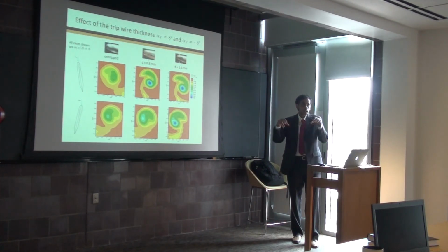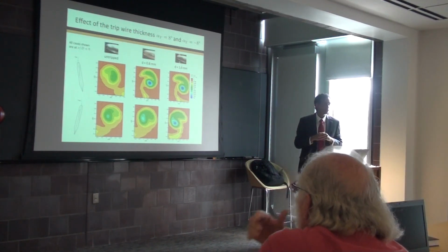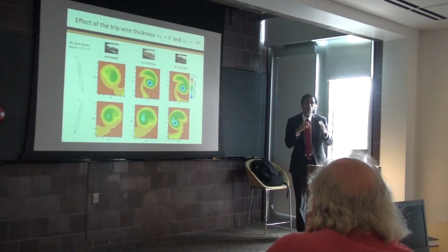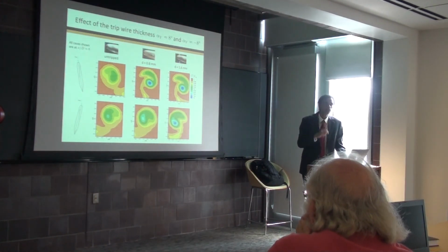Above that, there started to be an influence of the support, even in the pitch case. Implicitly, in the study that I've discussed today, I've basically assumed that the support doesn't have a role in pitch and only has a role in yaw. That whole thinking was based on this previous study at Virginia Tech by Roger Simpson's group. So we could do our own and see that for ourselves, particularly at high Reynolds number, because they weren't able to do that at high Reynolds number.